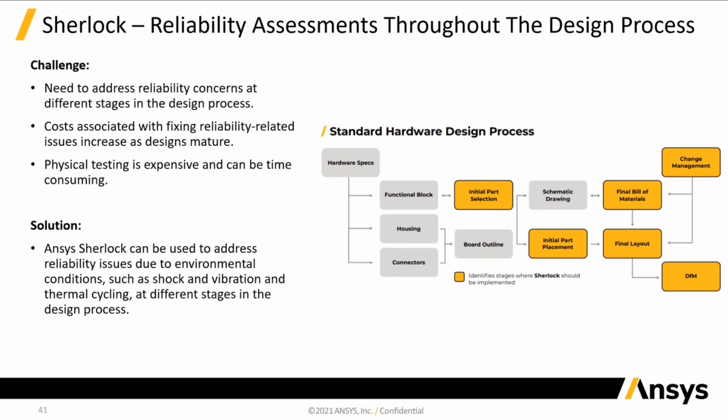You can even have an early arrangement on the printed circuit board because of where the components are going to be, so you can put components on. You've got an outline of the printed circuit board, and you can subject it to vibrational analysis and look at maybe where you put supports or do things like that.